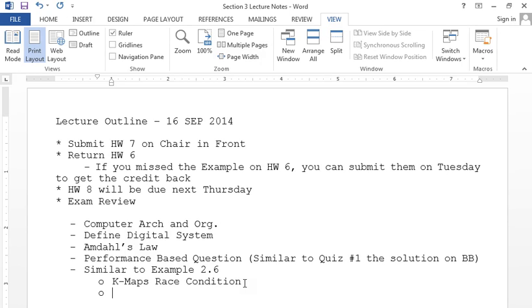And then you're going to calculate the input cost for the function of A and for the function of C, right? So you would do the K-map how? B is going to be your 0 and 1 variable, and AC would be your 00, 01, 11, 10. That's where, remember we were talking about gray code? That's where we're going to test your knowledge to properly do the gray code for the Shannon expansion. And then you would do the cost calculation.